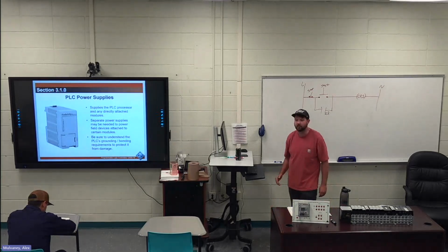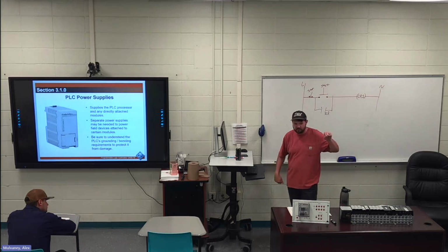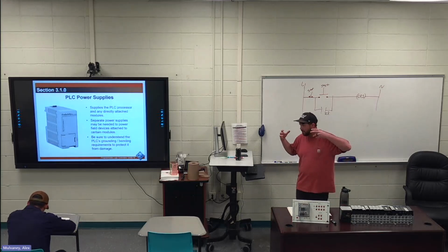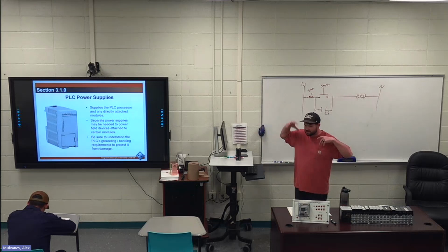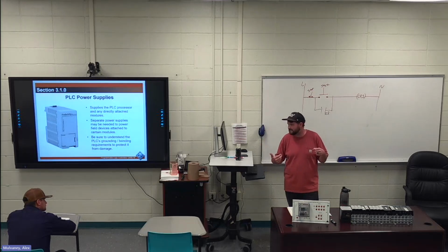So I kind of told you that wrong. I said it did top to bottom, left to right, but really it reads all the inputs, like what push buttons are pressed, who's pressing what on an HMI, what the level controller is doing. It sends that to the brain, and then the outputs go out, and that's a constant cycle that's happening. The PLC did that 1,000 times in the time it took me to describe how it worked. It does this almost instantly.